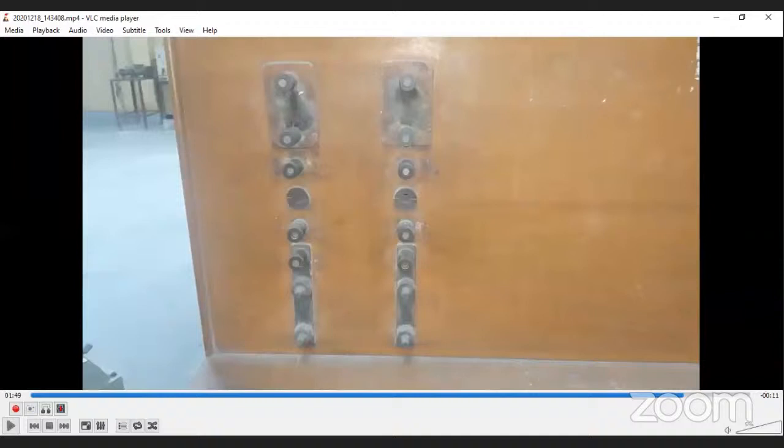Can you tell me how these discontinuities are used during connections? Anybody? It's a parallel connection. No. These discontinuities are used for the series connection. Suppose we want to connect some series apparatus like an ammeter or current coil. Connect an ammeter. Yes. Ammeter or current coil, because the ammeter is a series apparatus.